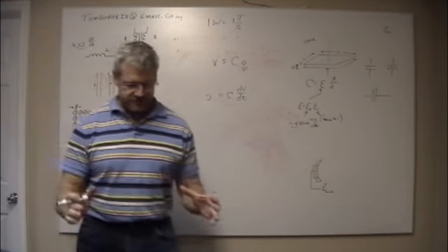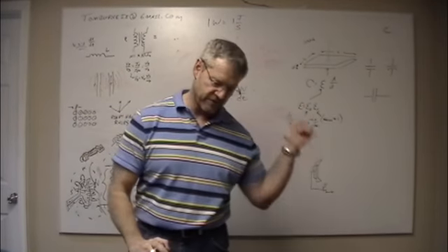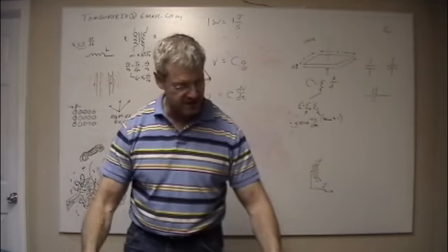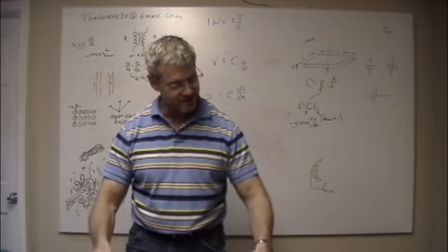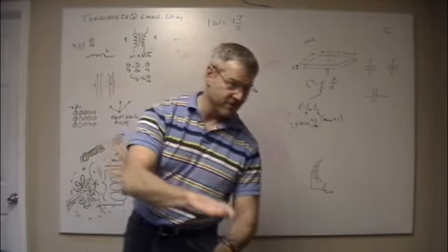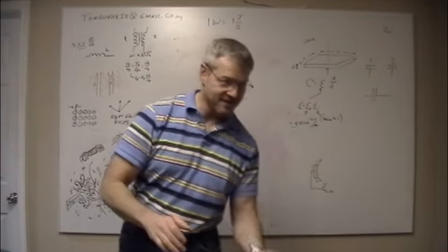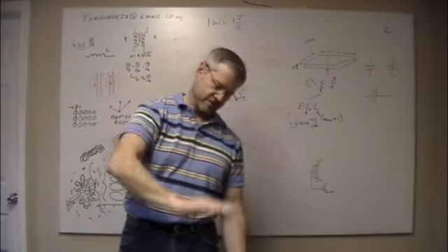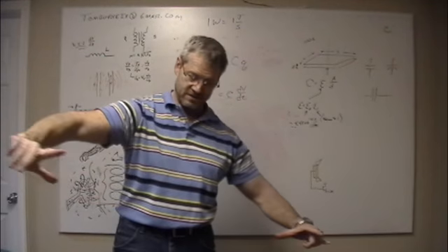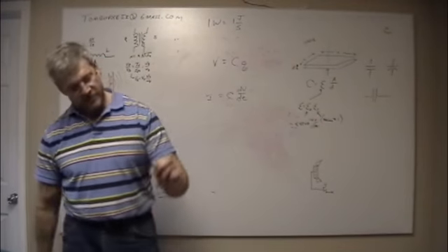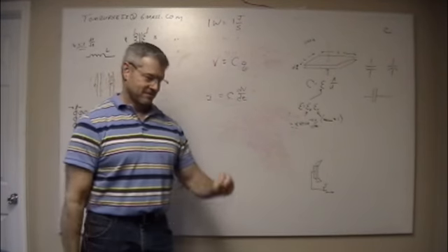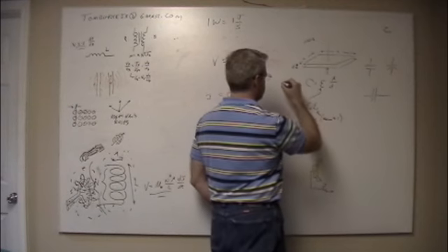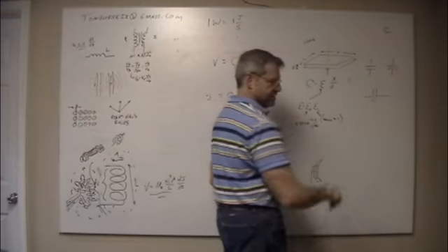So I've seen some stuff that people have done, Ben Franklin and company and Faraday and all those guys did some stuff a long time ago where they would lay down a sheet of foil and lay down a piece of glass, and lay down a sheet of foil, lay down a piece of glass, and they would take this piece of foil and wrap it over this one, and then they'd lay down a piece of glass, and take this other piece of foil sticking off from there and wrap it over this one. So they made a plate capacitor that was maybe 10 or 12 sheets of glass thick and this big. And you can go through and measure the distance. Oh, glass is 1/8 of an inch thick. So you come here and you say, this is a meter on a side, so that's 1, and the distance is 1/8 is what?